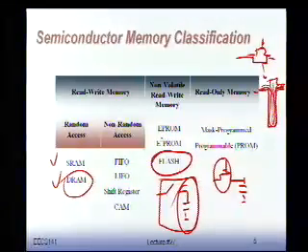Very tricky, as you can imagine. Very different than your normal logic process. So again, if I would try to do very dense DRAM together with logic, it creates a much more complex process. The yield is going down, the cost goes up. So typically we don't put DRAM on a chip either.